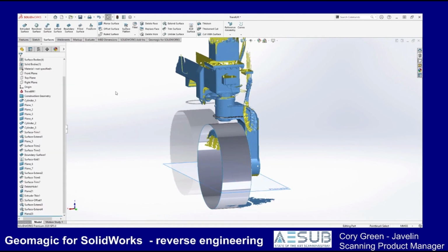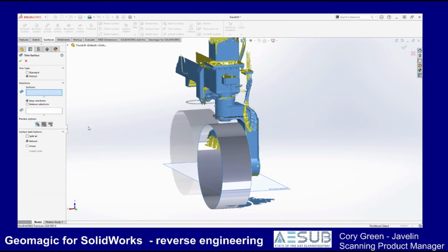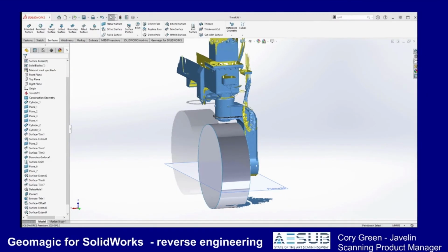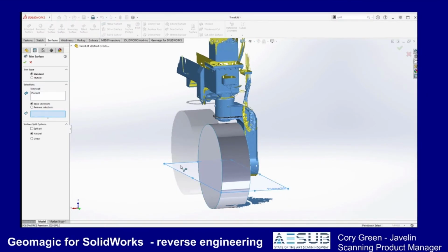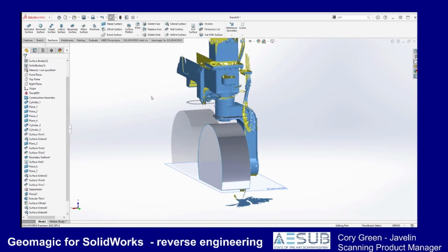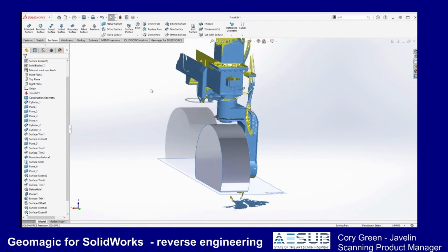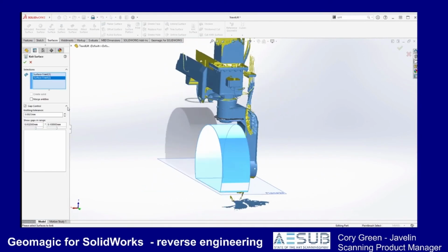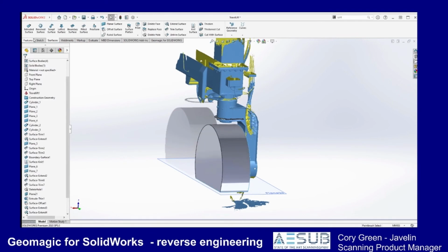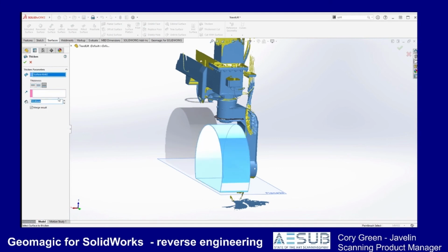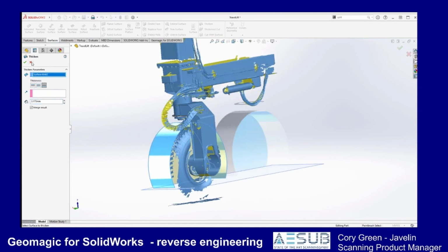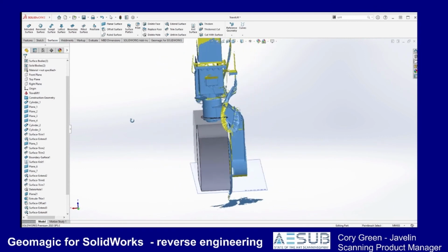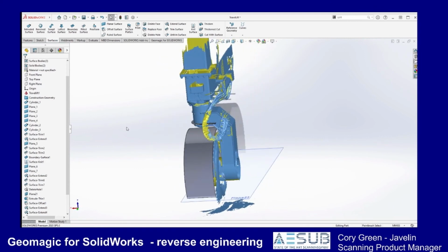We'll select a height that seems appropriate, and we'll use that to trim the cylinder that we created. We'll also fill in the inside surface. We can knit those two surfaces together and then thicken that to represent the sheet metal of the guarding. At that point, a very rough version of the fender has been created.